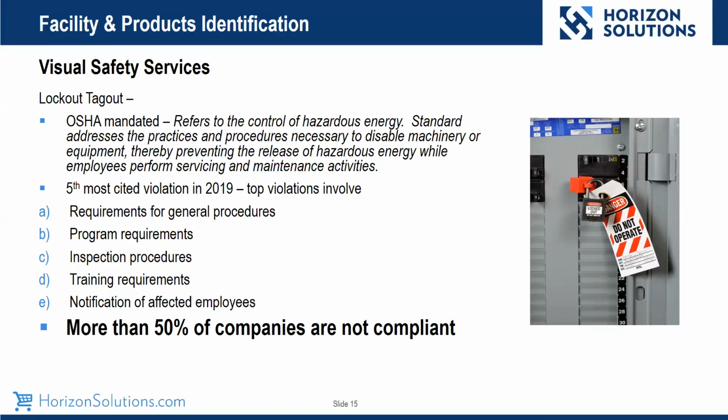I've paraphrased here, but Lockout Tagout refers to the control of hazardous energy. The standard addresses the practices and procedures that are necessary to disable machinery or equipment, thereby preventing the release of hazardous energy, right? That's while your employees are servicing, performing maintenance activities. Lockout Tagout is consistently in the 4th to 6th most cited violations. I believe it was the 5th most cited violation in 2019.